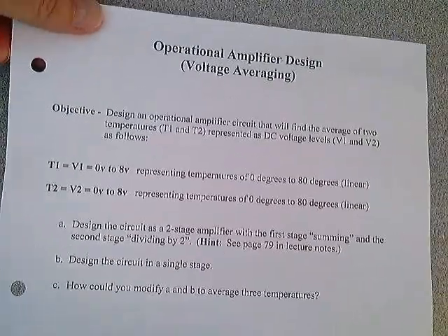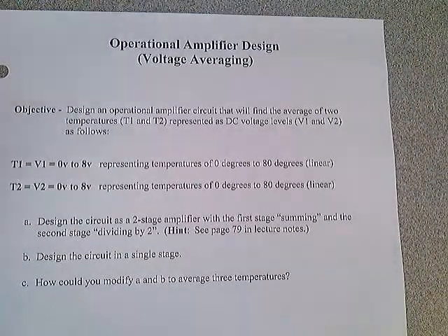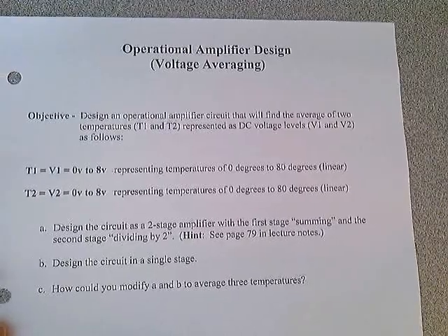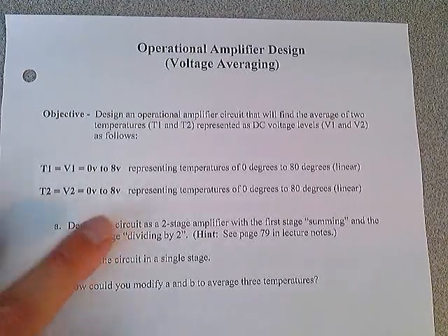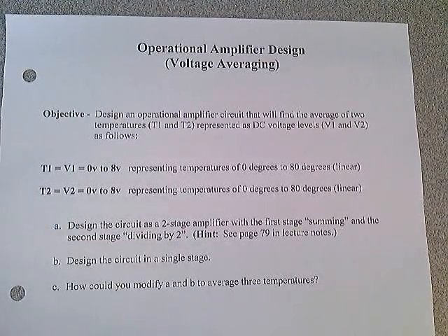operational amplifier circuits. I gave you a homework problem on voltage averaging. It's on page 81. I think this is going to help a lot with understanding how you can use op amps to do an engineering task out in the field. In this case, it was finding the average of two temperatures that are in two cylinders out on an oil field, or two pressures even that are out on an oil field, or the average of 3 or more. So you can display it. Make sure your process is running the way you expect it to run.